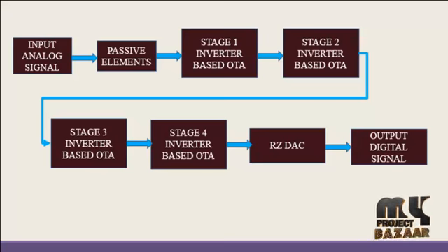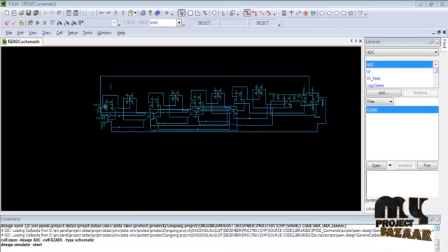There are several DAC architectures. The suitability of a DAC for a particular application is determined by three main parameters. First one, resolution, second one, maximum sampling frequency, and final one, accuracy. Due to the complexity and the need for matched components, all but the most specialized DACs are implemented as integrated circuits. Next we see about the running process of our product.